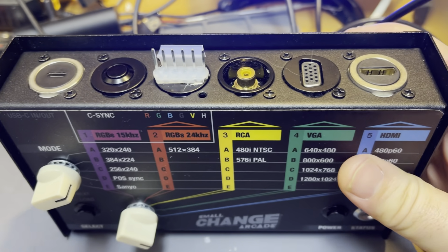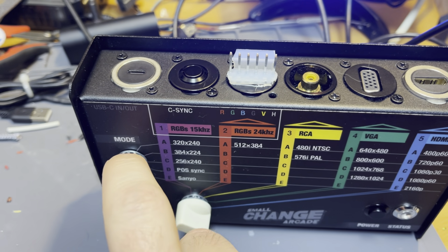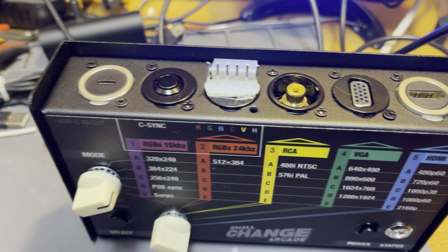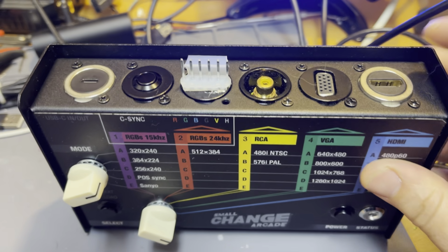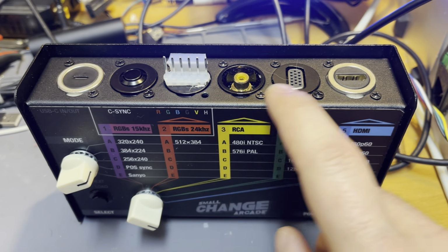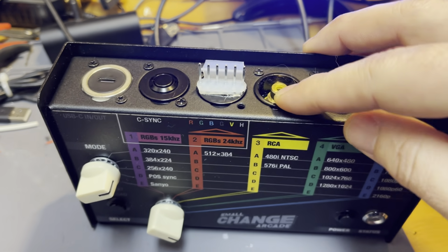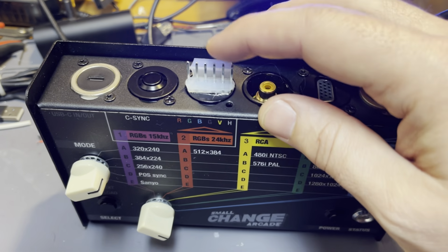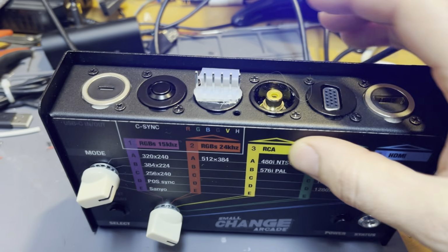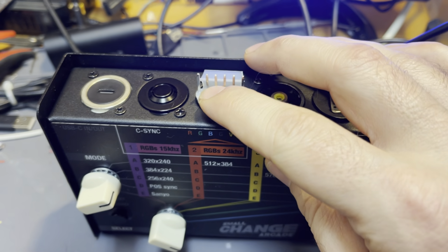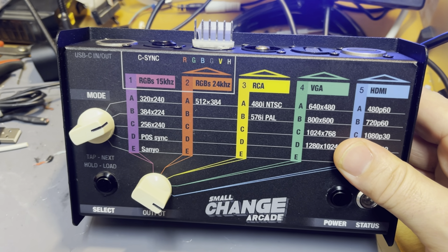So in the back here, we have all of our video outputs, and then we have a USB-C power in. I was originally going to put a battery in here, but I ran out of room, so now I just plug it in externally with the USB power source. And then over here, we have our different outputs. We have an HDMI output, VGA, composite, RCA output, and then this is just a standard 0.156 Molex for RGBS output, which would go to an arcade monitor, or you could even output from here to a SCART connector for a TV that has a SCART input.